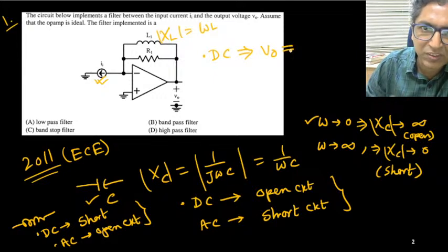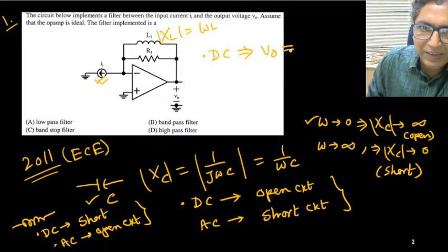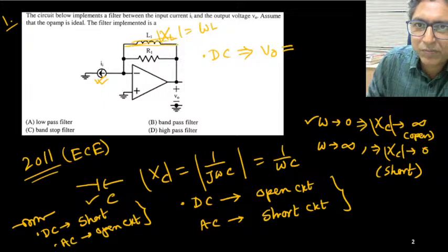Anyone can tell me, please? If the current source is DC current, means zero frequency, at that time what will happen in the circuit and what is the output voltage? So you can see that for DC, this inductor is behaving as short circuit. If it is shorted, the full current will pass through this side, it is fine. But there is no potential drop across this one.